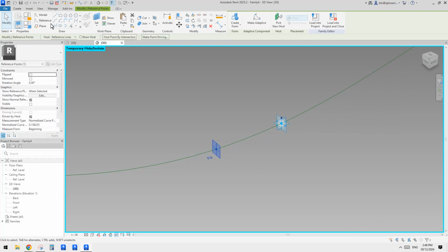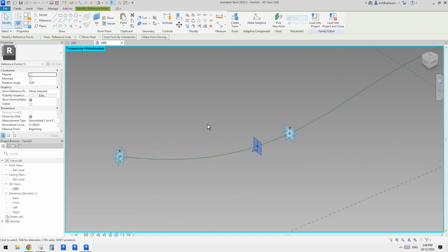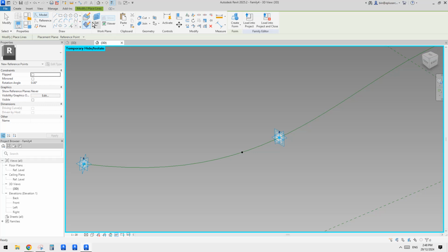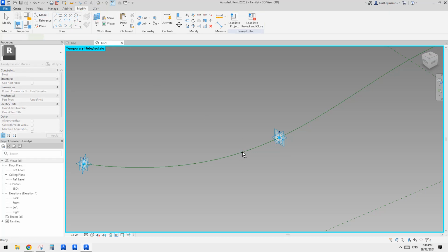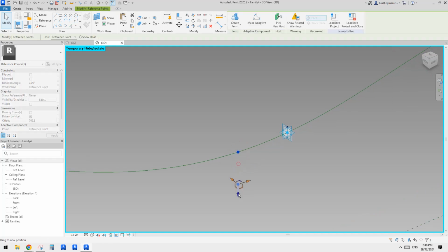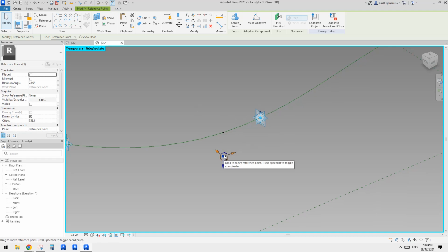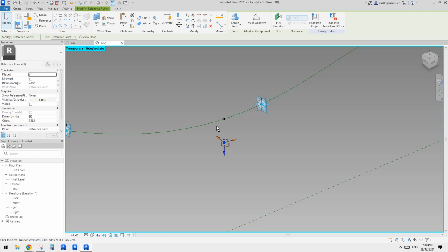And then we can just use another point. Hang on, let me think. When we place this one, we just place a point, use draw on work plane, set work plane, pick the horizontal work plane, and place onto the point again. So this one, drag this down, offset. Actually, let me think. Do we need to do this? Maybe not.